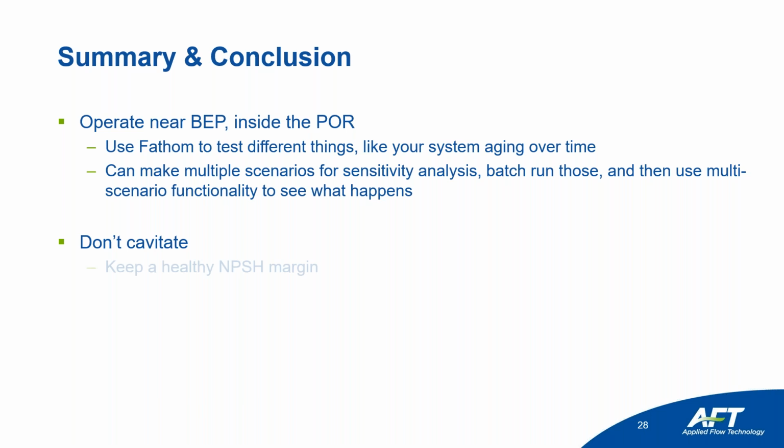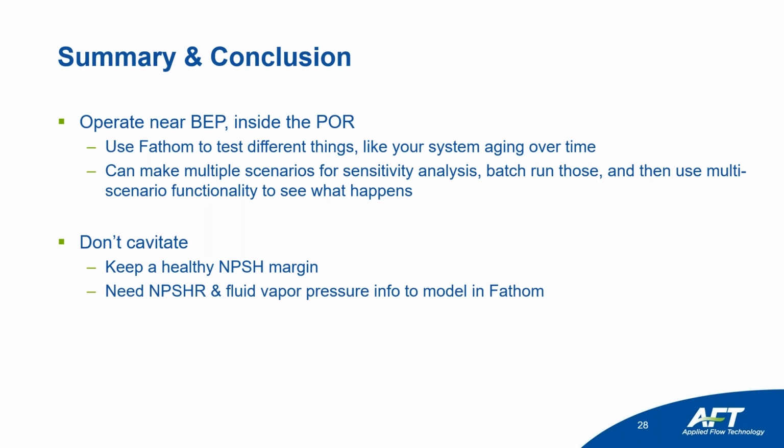Second thing was, don't cavitate. Keep a healthy NPSH margin. We saw that it is the suction side definitions that's going to change your NPSH-A. If your pump is the same, that's going to be what causes cavitation. You want a healthy margin. So again, what scenarios are useful for is comparing different operating conditions. You want a healthy margin.